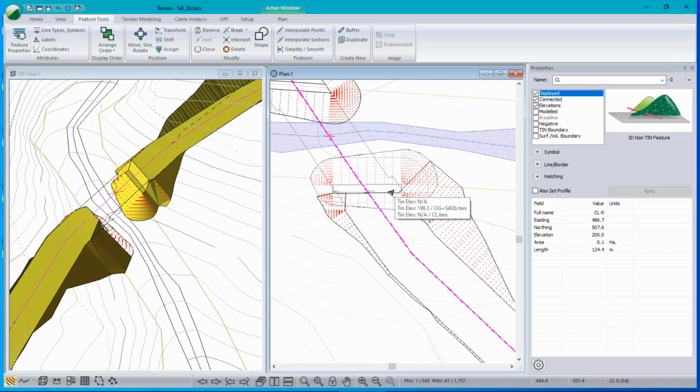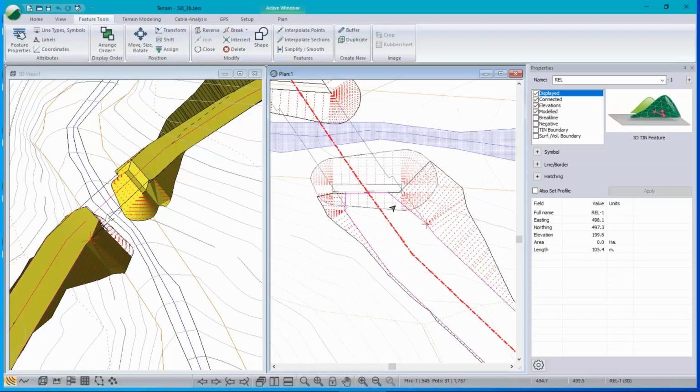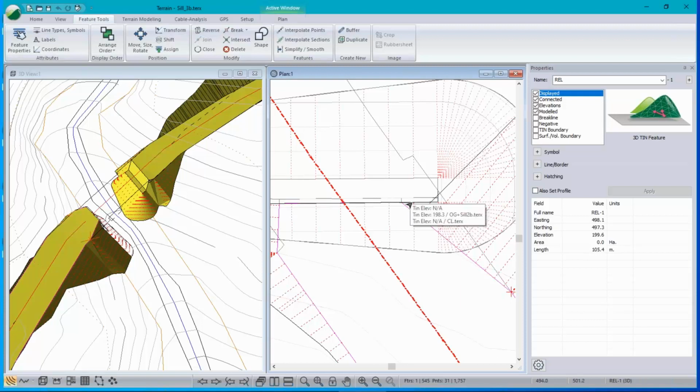And that's actually a merged surface. So the original ground plus the sill that I created in the previous one. And then I drew this feature here, which started out as an export from location, and I tied it off right to the edge of the sill feature, and then I graded it out.